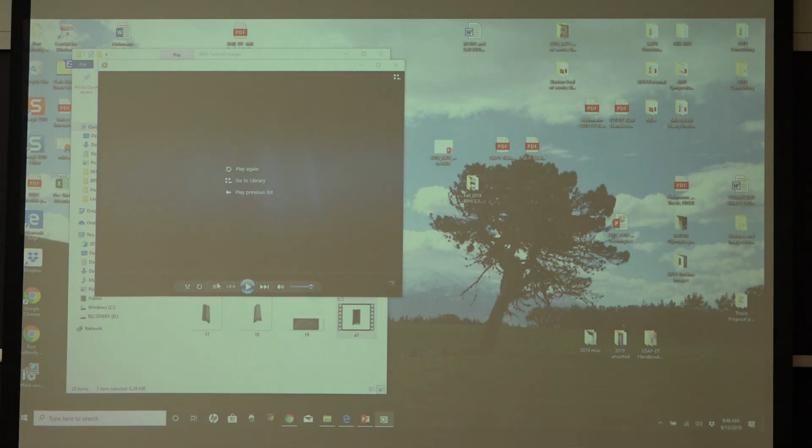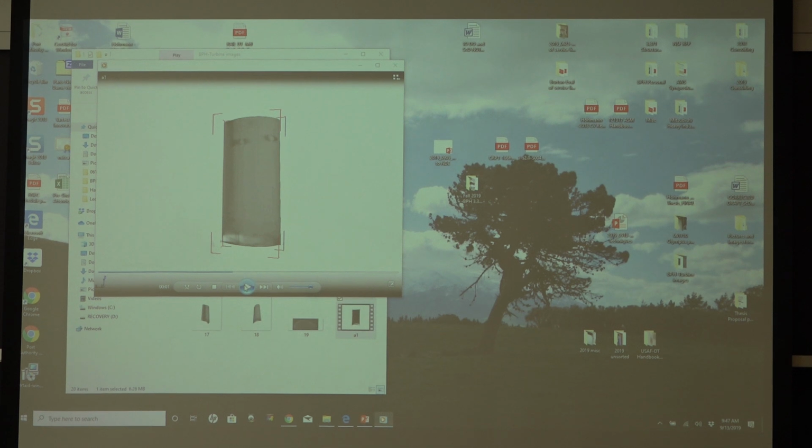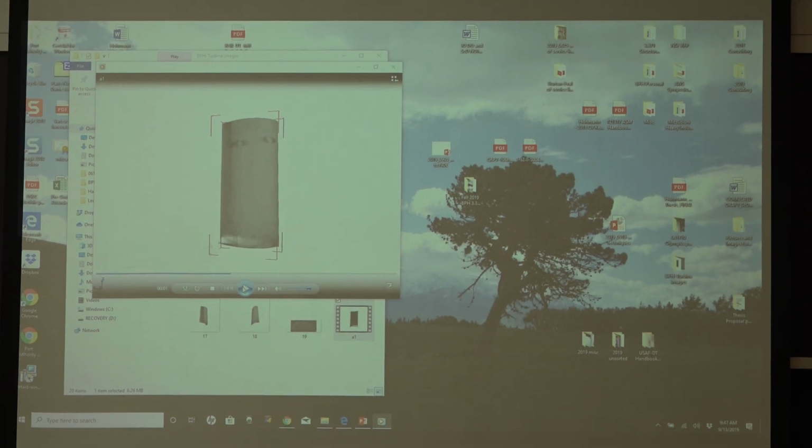That sample there was the sample I showed earlier, where you'll see these are the 2 areas that were pointed out by the inspector. The CT scan actually shows them, and it has more clarity than other techniques because of that focal spot size, so you can get a finer resolution of the microstructure.